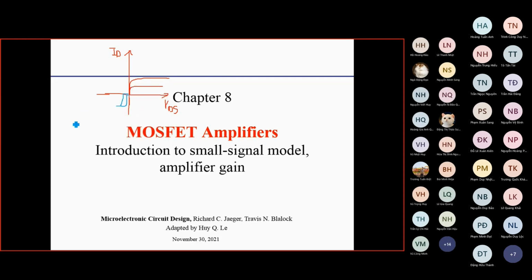For the field effect transistor, we can draw the gate here, the drain here, and the source here. We are considering the N-type, so the body is P-type. That means the majority charge carrier is holes, and the minority charge carrier is electrons. When you apply a positive VGS larger than the threshold, you can attract electrons to form the channel, so negative charge forms the channel.